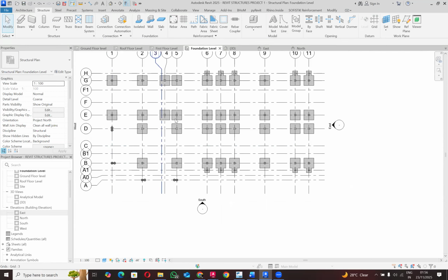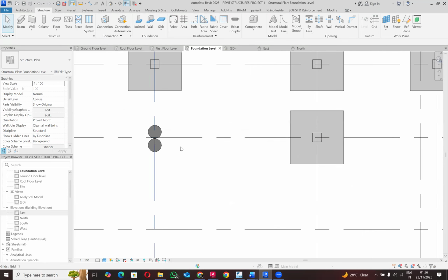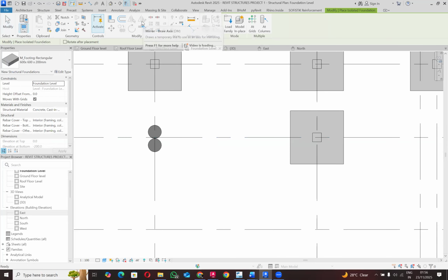Okay, so now we come to our combined footing here because we have two columns together, right? And these two columns might carry different weights. I know that the CG for your load and the CG for the footing should coincide. We have to do that mathematical calculation to make sure that you have done it precisely the way you're supposed to do it.